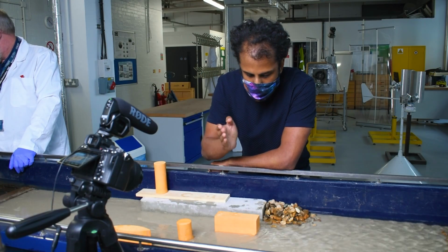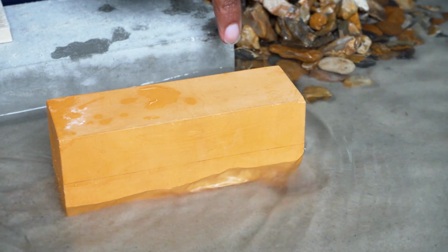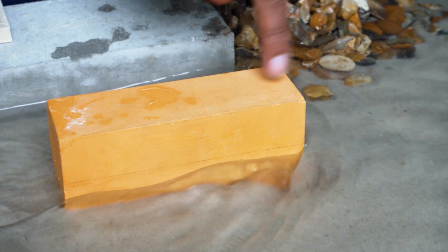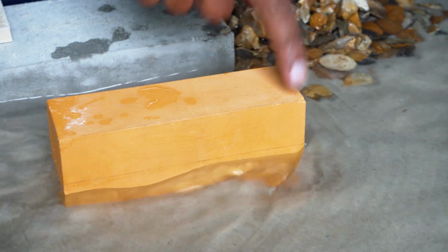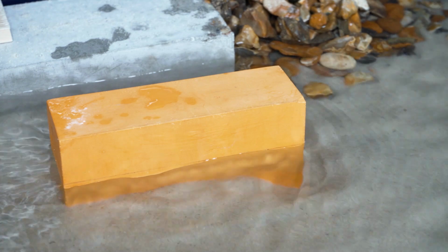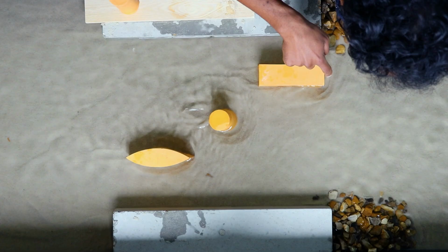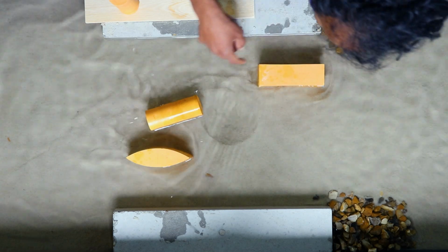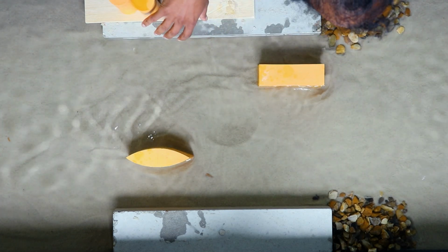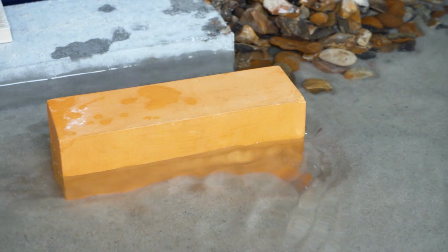Right, so let's focus on this structure as the flow's approaching. Now you can see very clearly already there's a significant scour hole that has developed on the leading corners. You can probably only see this corner, but it's symmetrical, so it's the same on the other one. What you can see is the flow's approaching. Oh, and on cue, our little cylinder pops out. The reason it popped out is that you can see there's a large scour hole that's developed already.